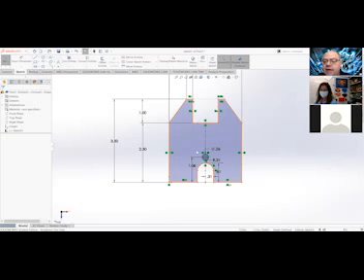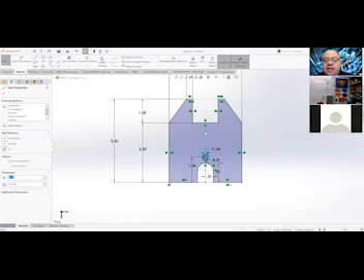Once you do that, everything's going to go black, except this little line here that's just an add-in. But that fixes the whole geometry, and so mathematically it's set. If you're a little worried about that, the one vertical center line you have down the middle is the one line you could throw an anchor down and fix it. That's a constraint. Again, you select the line and then just choose it from the relationship. So it's completely constrained.